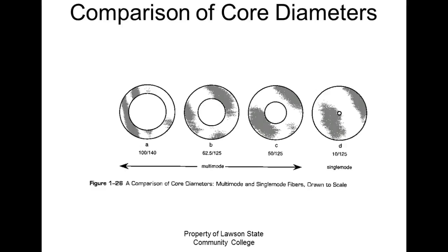So that's a times 100 fiber scope. We do have some times 200s, but when we use the times 200s, the core gets too big and we can't see the rest of the termination when we do it. So what we do is, did y'all see the scuff marks on there? When I pass those around, that's where it's actually sanded down. So we'll show you how to put those connectors on there and how to cut them.